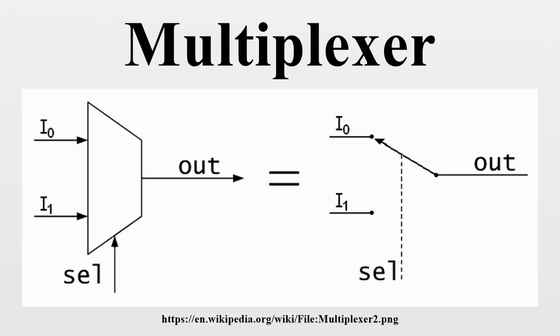Larger multiplexers are also common and, as stated above, require log base 2 of n selector pins for n inputs. Other common sizes are 4-to-1, 8-to-1, and 16-to-1. Since digital logic uses binary values, powers of 2 are used to maximally control a number of inputs for the given number of selector inputs. 4-to-1 mux, 8-to-1 mux, 16-to-1 mux. The Boolean equation for a 4-to-1 multiplexer is as follows. The following 4-to-1 multiplexer is constructed from 3-state buffers and AND gates. Note that the subscripts on the inputs indicate the decimal value of the binary control inputs at which that input is let through.